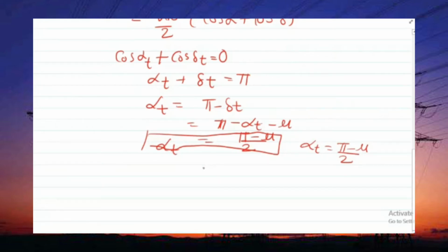For successful commutation, the changeover from the outgoing valve to the incoming valve must be complete before the commutating voltage becomes negative. For example, commutation from valve 1 to valve 3 is possible only when EB is more positive than EA. Here EB is the phase voltage of B and EA is the phase voltage of A, and therefore the current changeover from valve 1 to valve 3 must be complete before EA becomes more positive than EB, with sufficient margin to allow for valve deionization.